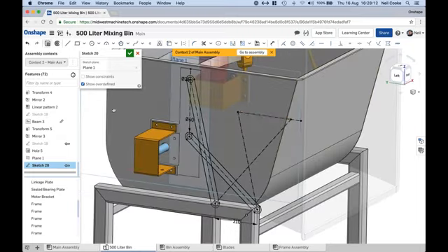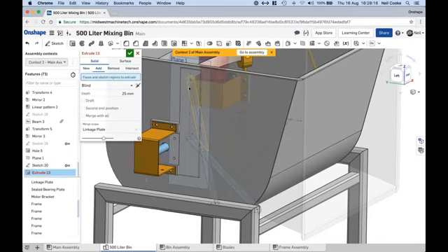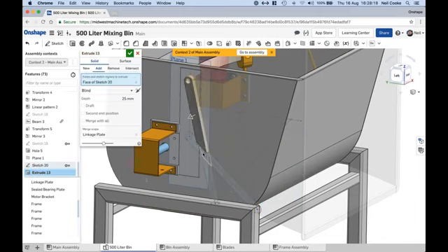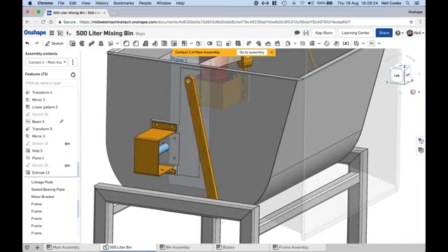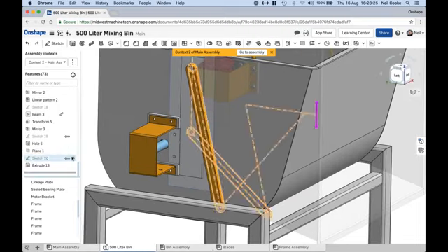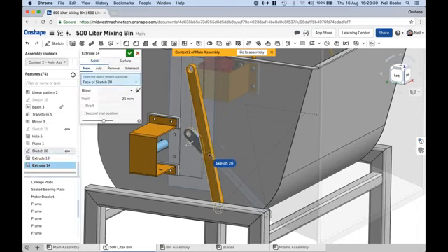All I need to do now is extrude the profiles that I want to use. So I'm going to use this one, and this one for one part, and let's make that 20 mil. That's going to be a brand new part. And then show the sketch again and create the other part, which is going to be this one.